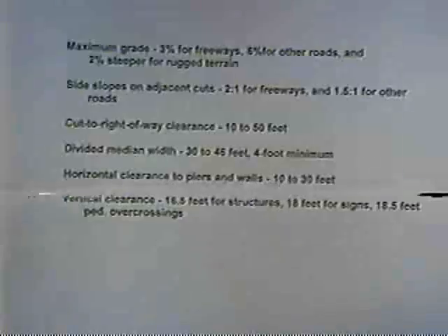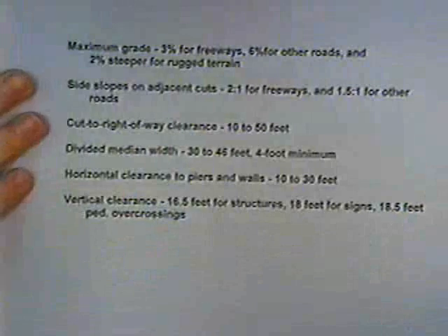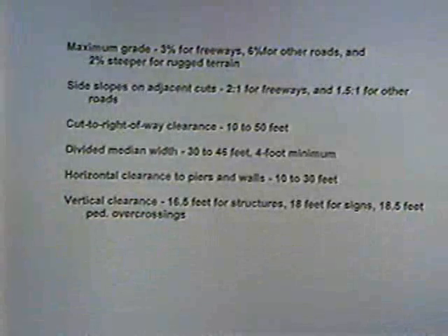There are some maximum allowable grades longitudinally along the roadways: 3% for freeways, 6% for other roads, and our design guidelines will allow us to go 2% steeper in mountainous or more rugged terrain. We limit our grades so that trucks can maintain speeds and not have to slow down to a crawl speed on our freeways or other major highways.